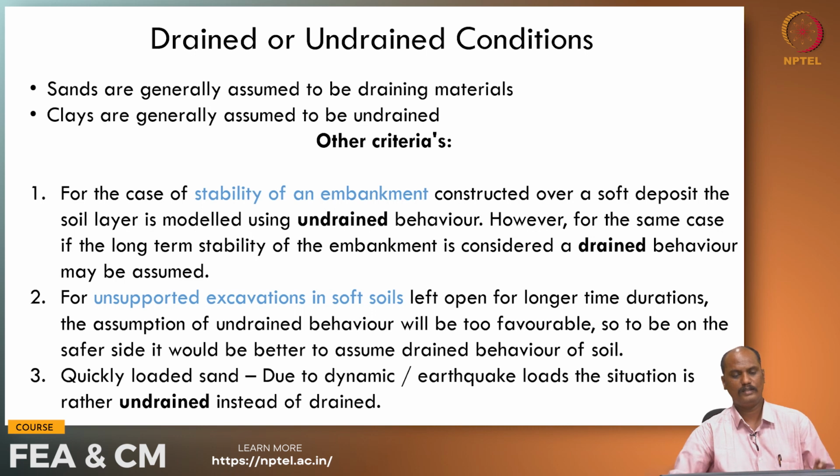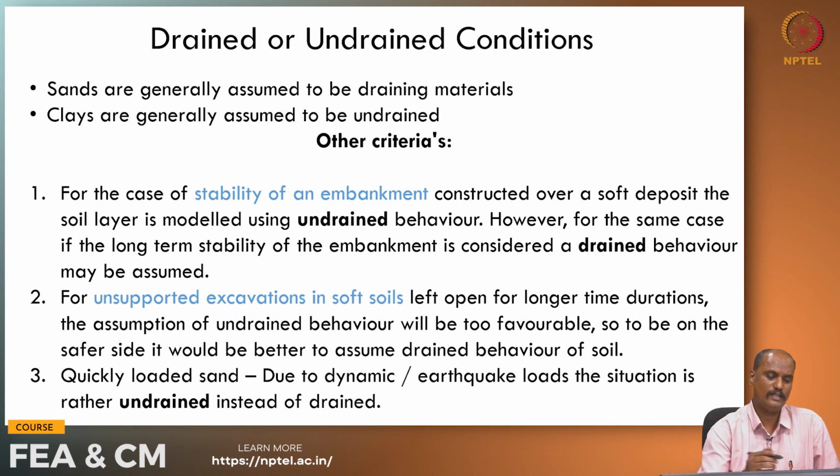Apart from all these things, I have just included some important aspects when it comes to modeling, especially in the case of undrained or drained behavior. We all know that sands are generally assumed to be free draining materials, so we can assume a drained behavior for sands, and for clays we generally assume undrained behavior. What I would like to say is, strictly we cannot say that sand should be modeled as drained and clay should be modeled as undrained.